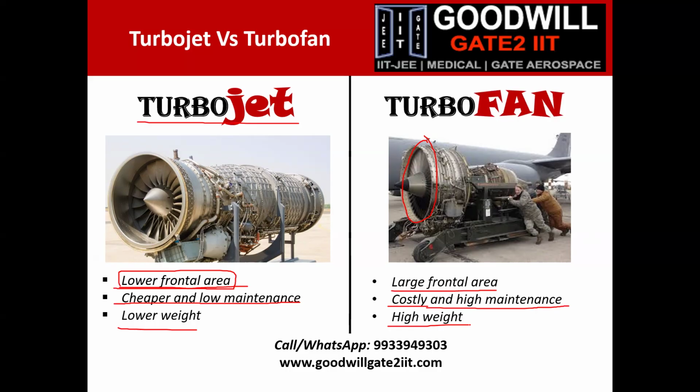Now, keeping these points in mind, you can understand a few things. Because there is low frontal area, there will be low drag. And if there is low drag, that means you can travel faster. So turbojet engines are basically used when you want to travel very fast, basically in fighter aircraft, when you want to travel at a Mach number of 2, 3 and higher.